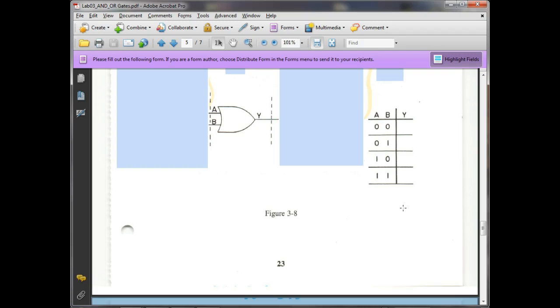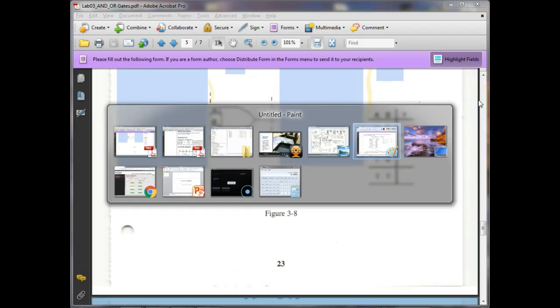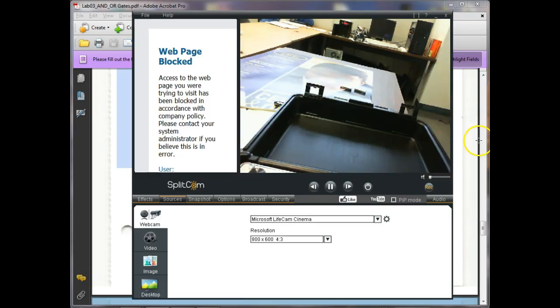So I've seen people do this. They say, I need a 10 kilohertz sine wave, and they'll come over here and be screwing around with their scope. And they say, I can't get 10 kilohertz, because they're trying to get it from the oscilloscope, and it don't generate the waveform. The oscilloscope measures the waveforms that's there. Okay. So where we're going to get our clock input at? Not from the oscilloscope. We're going to use the oscilloscope to measure it, but we're not going to get it from there.